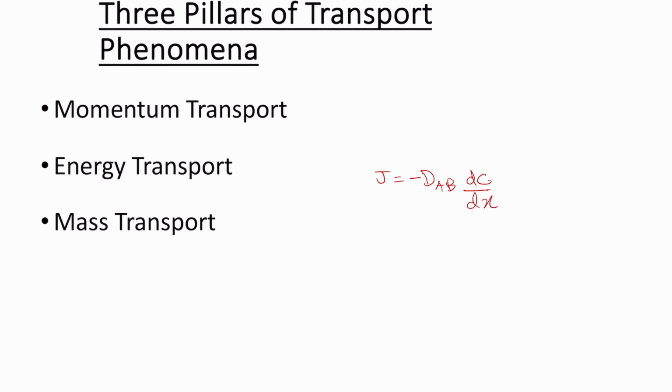Also, convection is mass transfer due to bulk movement of fluid, and combined convection-diffusion equations are used in many systems. Key concepts of mass transfer are diffusivity, that is DAB, which is a measure of how easily a substance diffuses into another. Mass transfer coefficient is used in convective mass transfer, along with dimensionless numbers such as Sherwood, Schmidt, and Peclet, which characterize mass transfer behavior. Applications of mass transfer are gas absorption and stripping processes, drug delivery in biological systems, membrane separation, distillation, and chromatography.